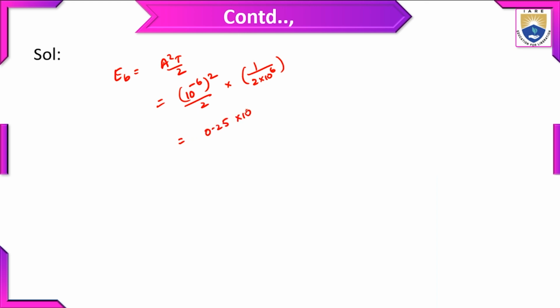That is equal to 0.25 into 10 to the power of minus 8 joules. So there is EB, energy of bit, that is equal to 0.25 into 10 to the power of minus 8 joules. Where N0 by 2 is equal to 10 to the power of minus 20, N0 is equal to 2 into 10 power minus 20. So this is my N0, noise spectral density. So here we are going to substitute EB value and N0 value in the probability of error.